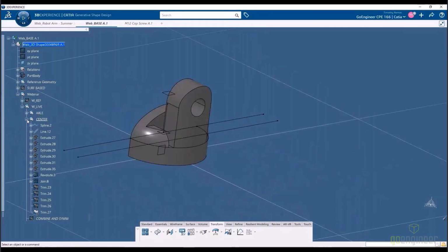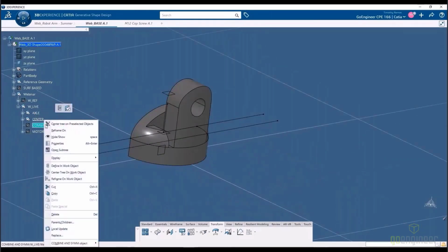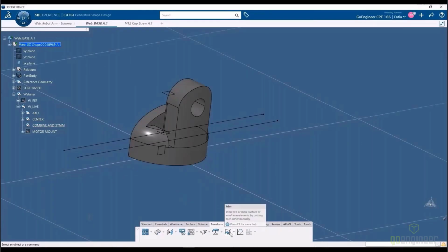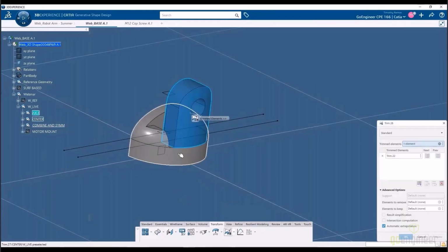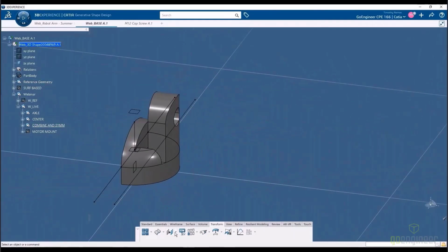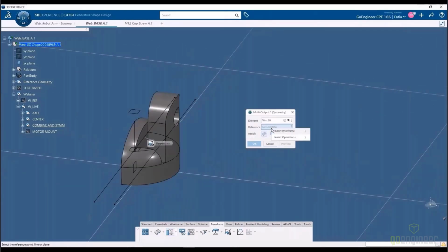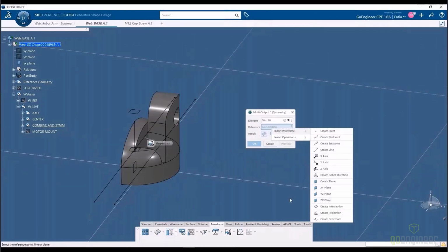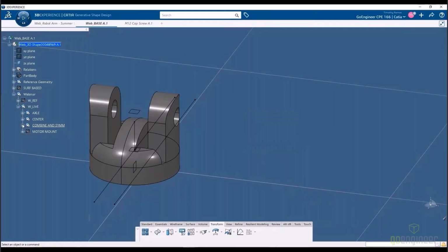Unhiding our axle mount, we can see that we fit this geometry sufficiently. Now I'm going to trim these surfaces together to make it one singular shape and remove the overlapping surfaces. And because this is symmetric about the ZX plane, I'm going to symmetrize it. One singular surface.